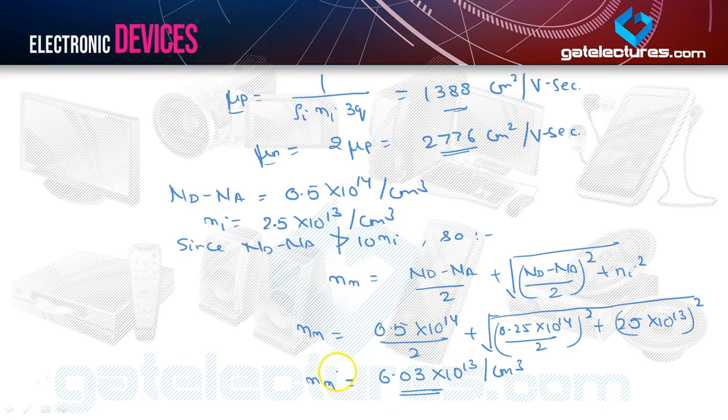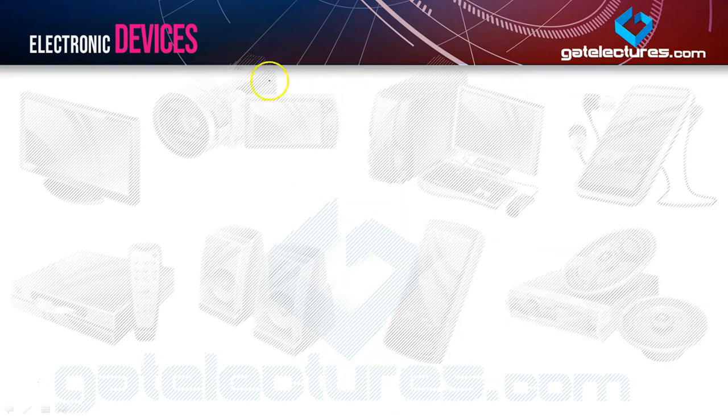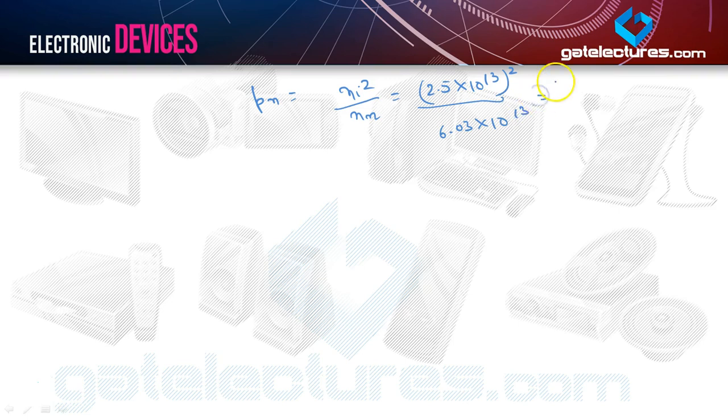So this is the electron concentration, and since it is an n-type semiconductor, we can find the hole concentration as ni squared by Nn. So this is (2.5 × 10^13)^2 divided by 6.03 × 10^13. When you solve it, you get 1.03 × 10^13 per centimeter cube. Now the current density.